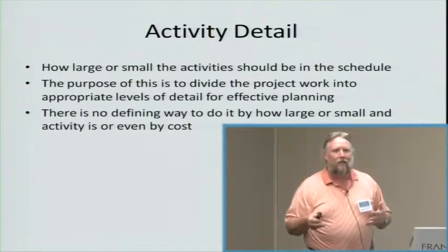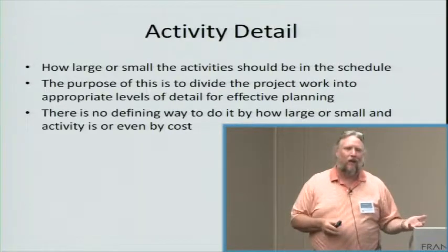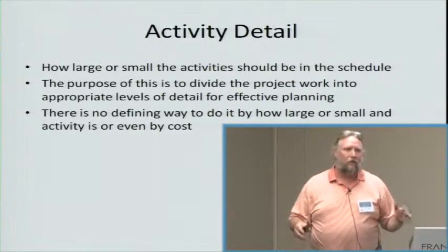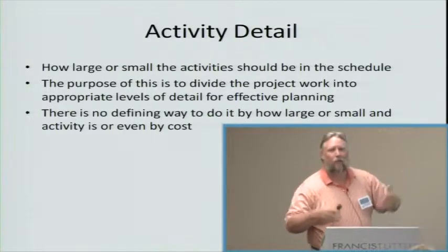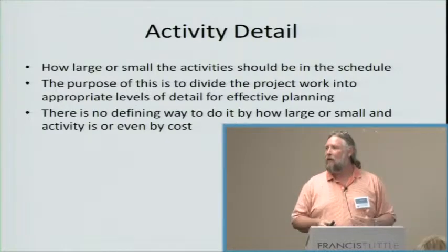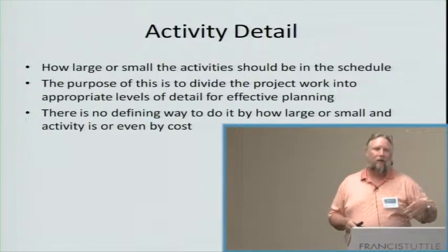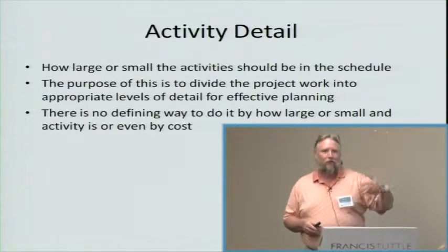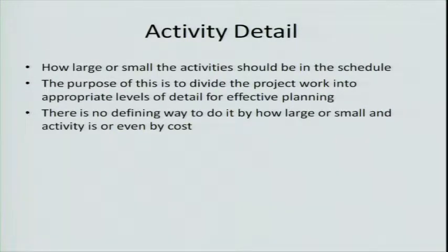the activities need to be what's necessary for your project. I can't tell you what size activities you need or what you want to do. We talked about grading and bridge, 2 activities. Maybe that's a little bit too big an area, so maybe we want smaller ones. The grading we're going to divide into stripping, clear and grub, subgrade preparation, cut and fill movement, and those things. So large or small depends on what the schedule looks like, on how detailed we want the schedule to be.